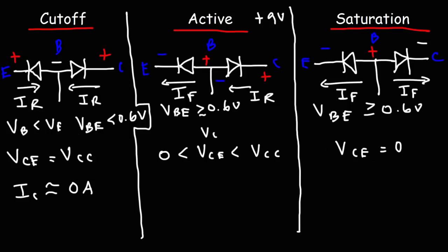So that's why it's important to know what the VCE value is, because by knowing it, you could determine if the transistor is operating in the cutoff region, in the active region, or in the saturation region. So VCE, knowing that value, is very important.